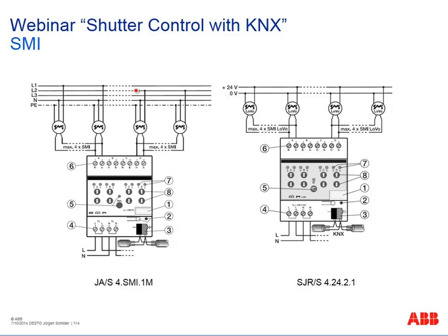At first, before that, again a slide about the wiring diagram. Here we have our actuator, then we have the 4 groups, the 4 outputs, and per output it is possible to connect in parallel up to 4 SMI motors, maybe to our output A or to our output D. And the same in our low voltage actuator. Our motors will be supplied via 24 volt DC, and via SMI they get the information, position, height, and can send back status.